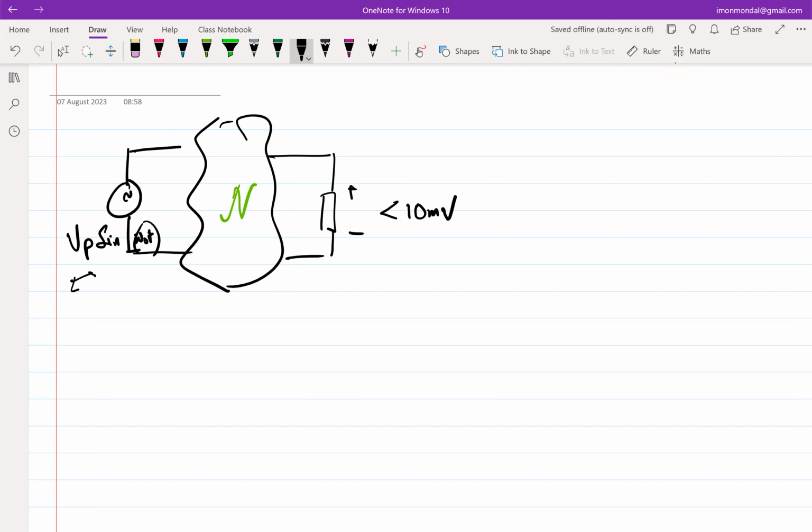One was partially algebraic, partially graphical: you plot the IV characteristics of the nonlinear device, superimpose it on top of the linear characteristics, and see where those two curves meet. That becomes my solution. And then on top of that, you can linearize the nonlinear device with its slope, and then find the output, assuming that the excursions are not large.